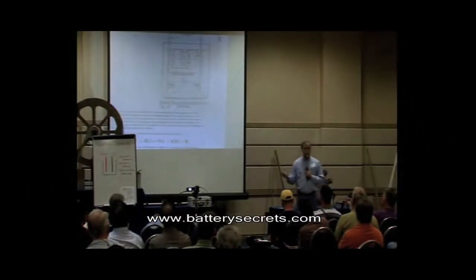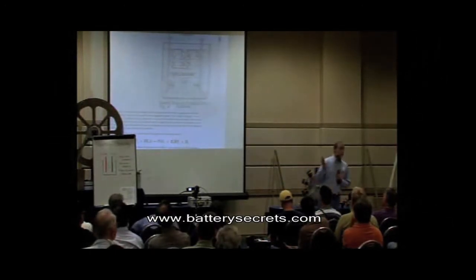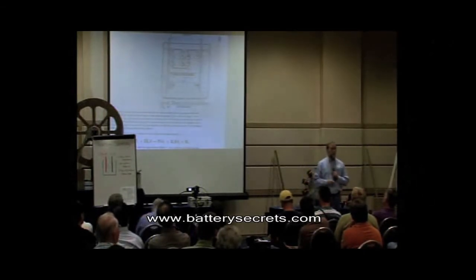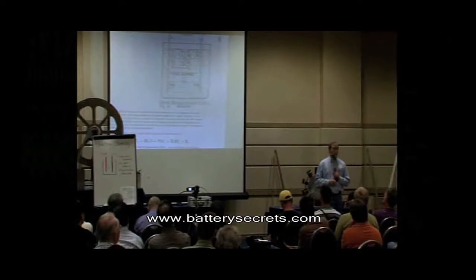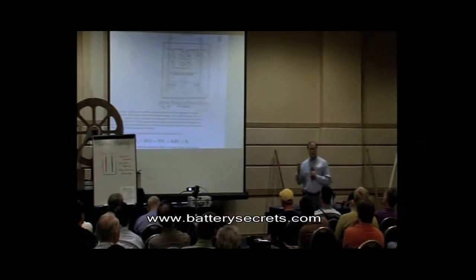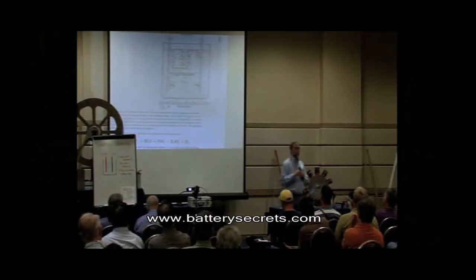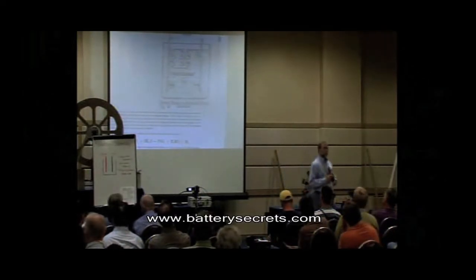But if you do that and call it an electrolysis cell, what happens is the hydrogen and oxygen off-gas as gases. And if that happens in your battery, you just poured electricity into this thing and didn't charge it. We need something completely different to happen than that during charge.